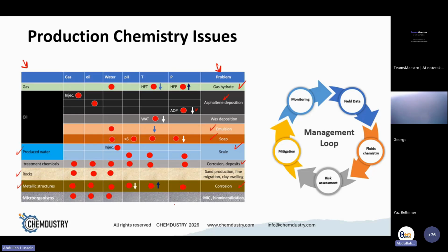And sometimes it can even get worse, because a problem can induce another problem. Corrosion can induce scale. Scale can induce corrosion. Bacteria can induce both of these, scale and corrosion. And it can get even worse, because sometimes we inject chemicals for treatment, like corrosion inhibitors. We inject these to mitigate the corrosion, but sometimes they have surfactancy in them, so they can actually stabilize emulsions for you.